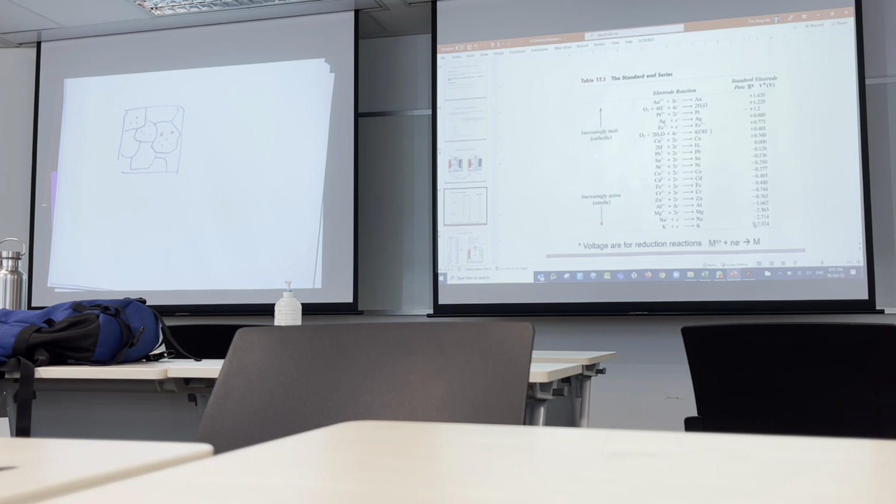And when you look at the dislocation, remember, along the line, there will be a whole column of atoms that is not satisfied, right? The topmost one is preferentially attacked. This is the part where I look down from the edge dislocation. Okay, remember? I will attack here. This is the non-favorable side. So anything that is non-bulk, not highly coordinated, will always be preferentially attacked. So imagine this is at the surface, right? This will be the one that's being attacked.